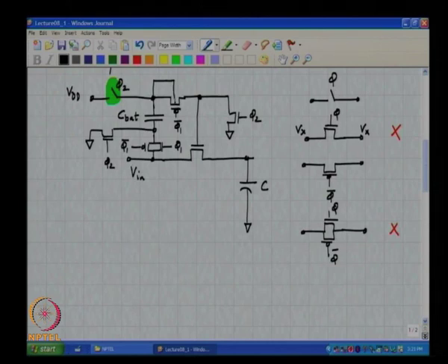Please note that this is somewhat of a departure from normal practice. Normally in digital circuits, what would you do? You would, without thinking, simply connect the body of the PMOS transistor to VDD, and the body of the NMOS transistors to ground. In many technologies you do not have any choice at all, it is automatically ground. And why do you normally connect the body of the PMOS transistor to VDD? Because you expect that no node voltage inside the circuit exceeds VDD. So, VDD is a safe place to tie the body of the PMOS transistor.